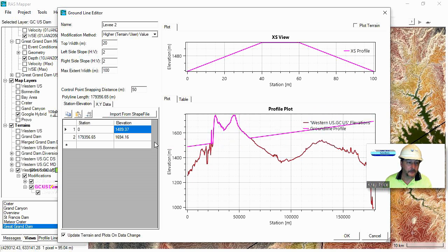But again, I had it going the other way before, so I'm going to take this one from an elevation of, say, 1250. So I'll take this one here, make it 1250, and then down at the bottom end here, I'll make it 1000. And in this case, again, I just do everything like I did with the dam, but I'm going to do it upside down. So with that, I should see a channel now going from one end to the other.